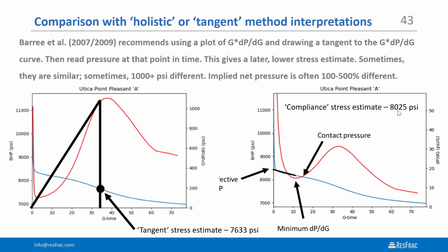But let's consider the estimate of net pressure. So net pressure is the difference in pressure minus Shmin, and that's what determines fracture aperture and fracture size. So again, I'll talk about the near wellbore tortuosity in a minute, but our best estimate for fluid pressure in the fracture after shut-in is maybe 8,400.